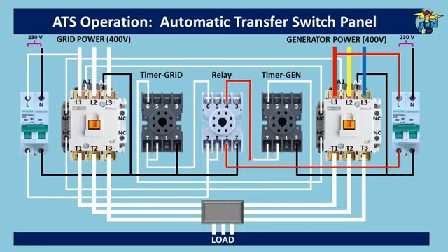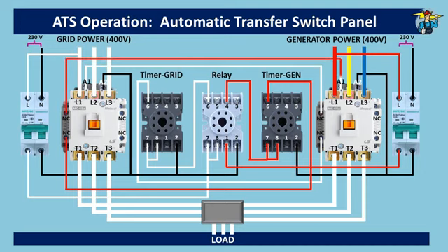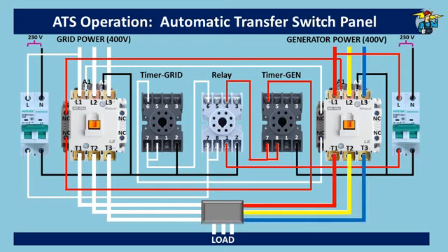allows power at number 1 of the relay to flow to the number 7 and 8 of the generator timer. Although the relay is powerless yet, the generator timer is powered now, and after the set delay time on it, number 6 also gets power, thus allowing connection to the A1 of the generator contactor. This connection too goes through the normally closed auxiliary contact of the grid power contactor to make sure it is at off position. This allows the generator contactor to on position, and the load gets 3-phase power through the generator now, and will run like this till grid power is restored.